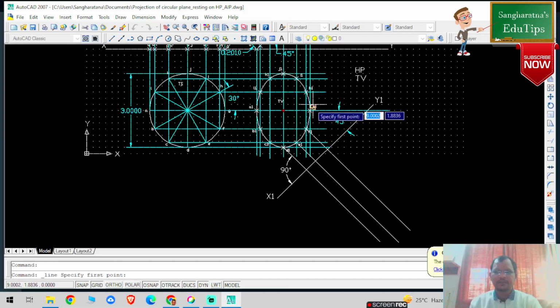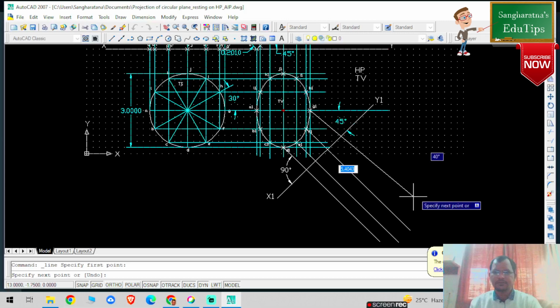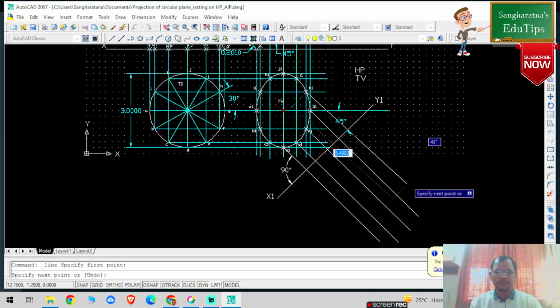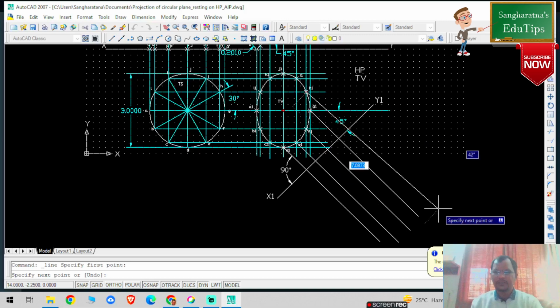Similarly, from all the points you need to repeat this particular step, to your students. This will pass through all these points. If you check, this is passing through this. So this is basically 6, press tab, this will be 45. Again select from this particular point; from all the points you need to draw the projectors. Then only your problem statement will look correct.